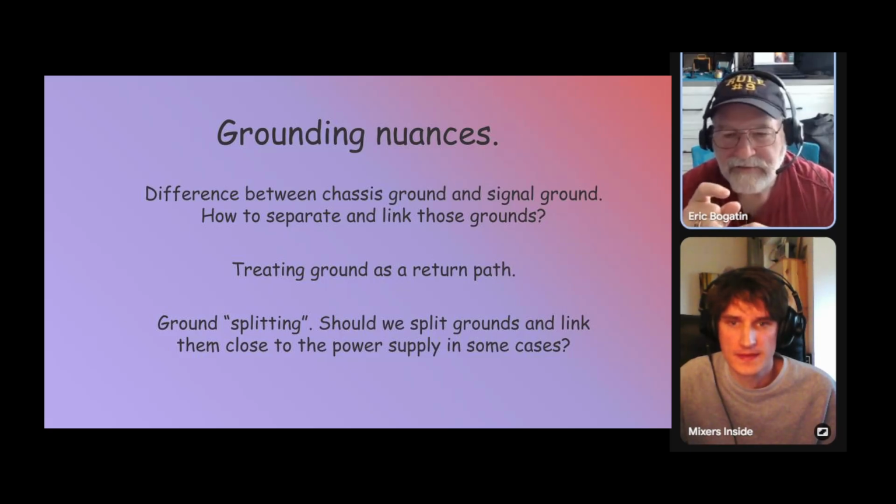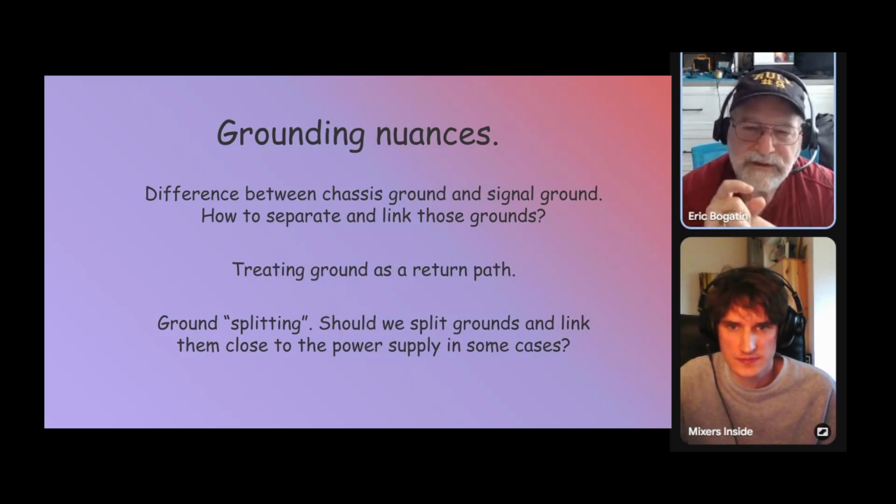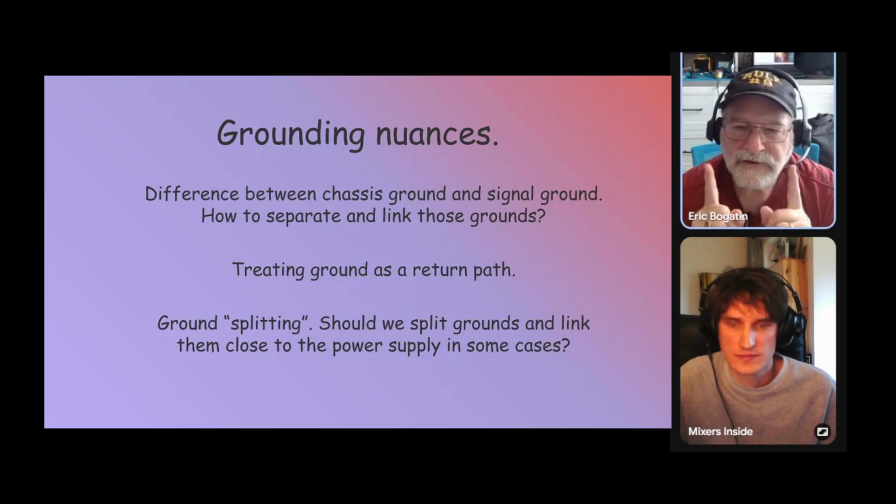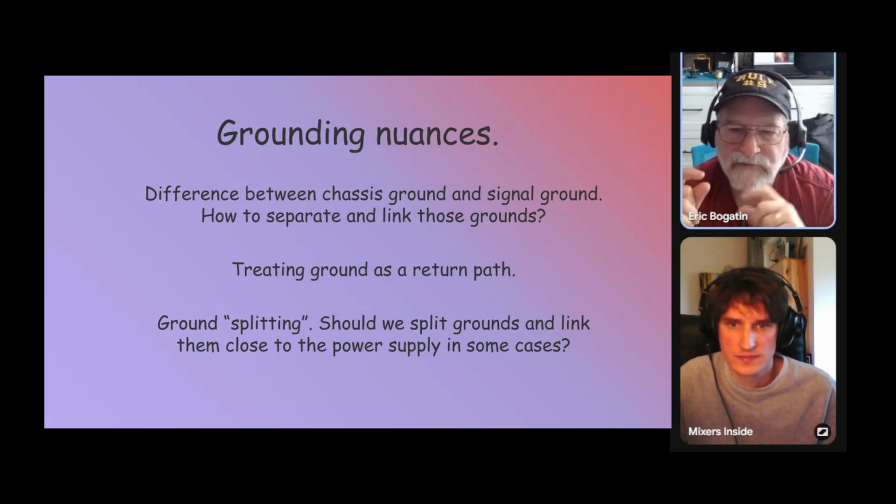The connection between the microphone and the amplifier is one trace, and the return connection from the microphone ground, or the ground reference, is another trace that goes to the input of the amplifier. If there's no current through that trace, there's no voltage drop, and we're seeing at the amplifier the same voltage as at the microphone.